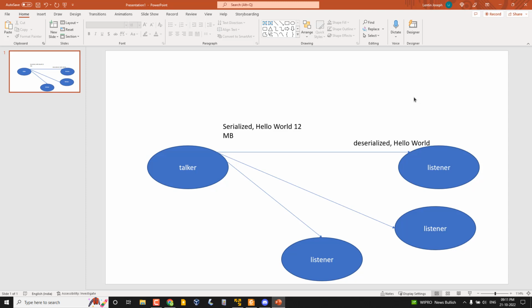That's where the Nodelet's importance comes in. So here I mentioned that if you are writing nodes like talker and listener, these are all separate processes. Talker is a process, listener is a process. These 3 listeners are independent, individual processes running, communicating over sockets and serialization, and it will take CPU.